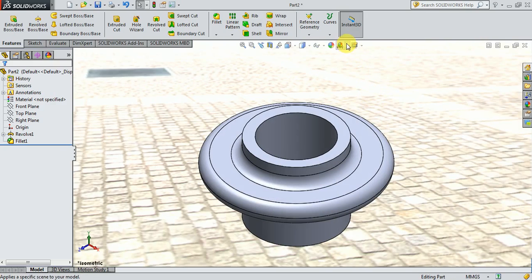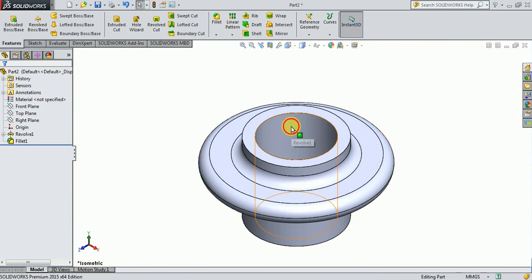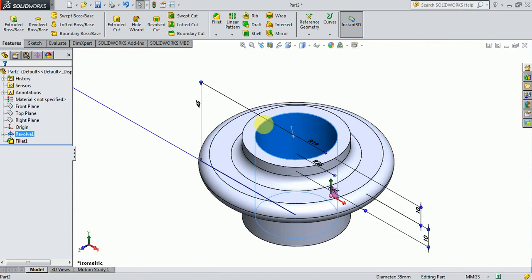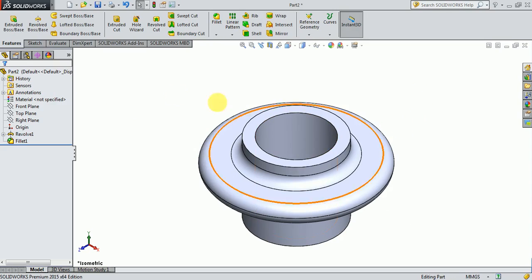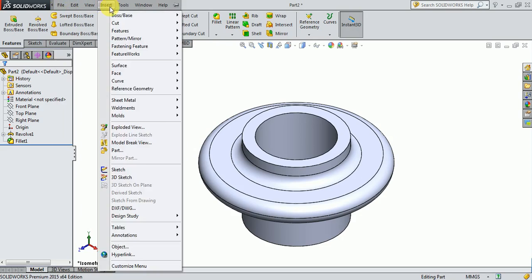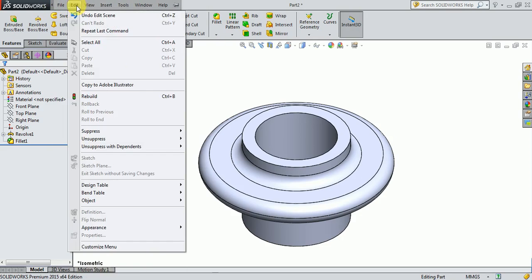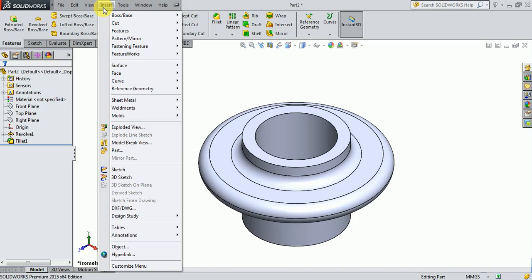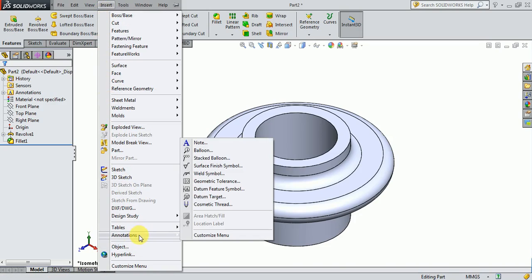Is it not? So in the same way, now I am going to change the graphics of the inner surface of this nut. I will explain now how it can be done. You just take the cursor to SolidWorks, then these hidden menus will appear. Go to this pop-out menu here, and under that go to Insert, then under the Insert menu go to Annotations, and choose Cosmetic Thread.